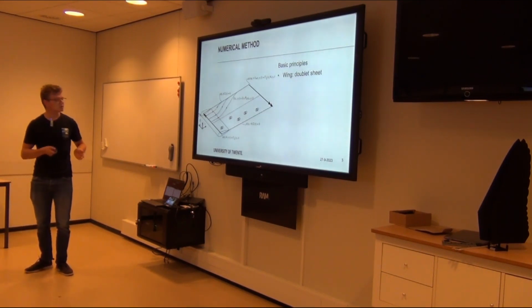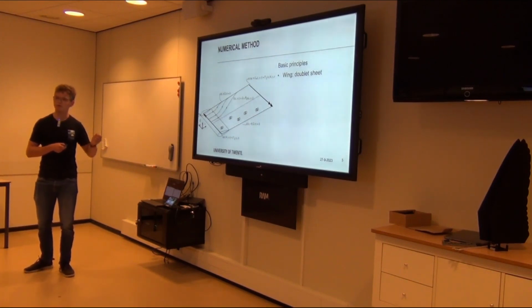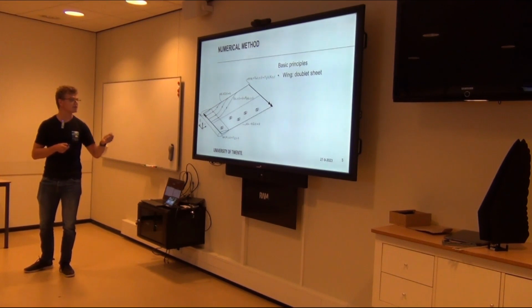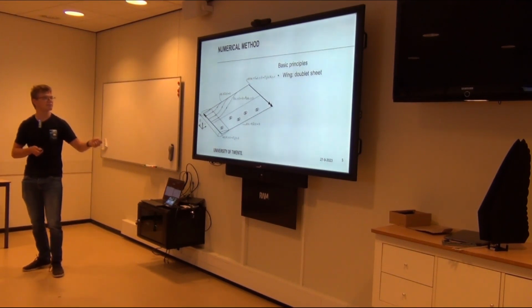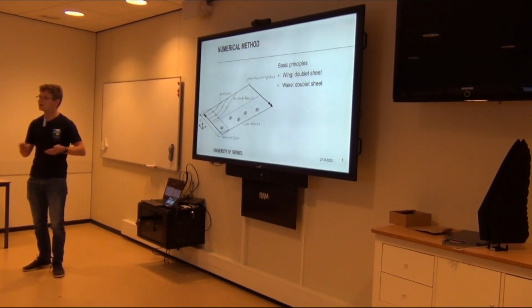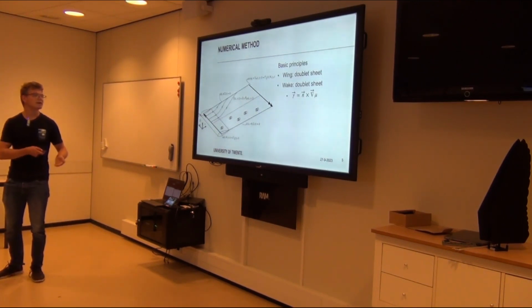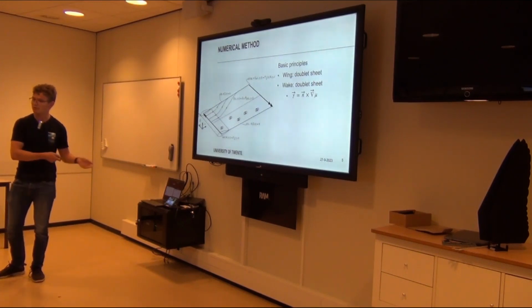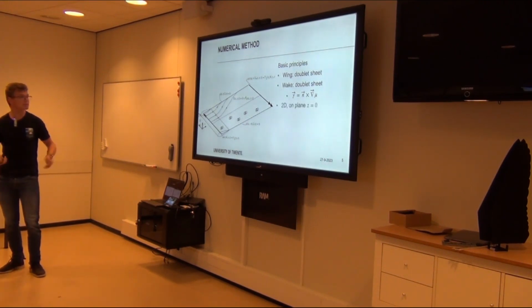To then close the model to our wake model, we modeled the rest of the wing, from our lifting filament to the trailing edge, as a doublet sheet. The wake itself, again, is a doublet sheet. Using this analogy, we can then simulate vortex shedding from the wing into this wake. So there you have your complete wake model, so to say.